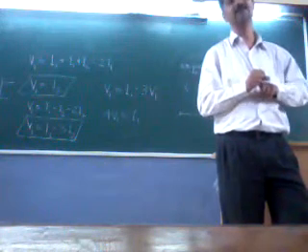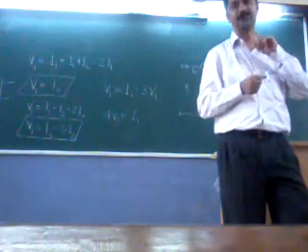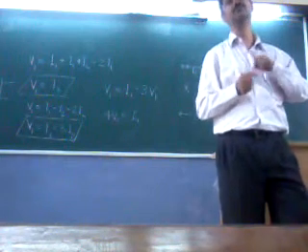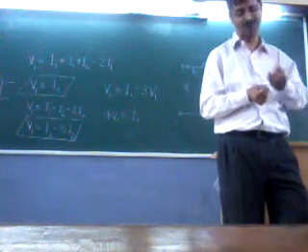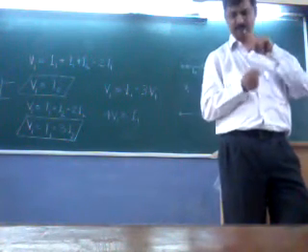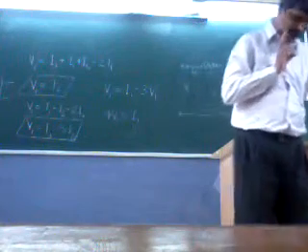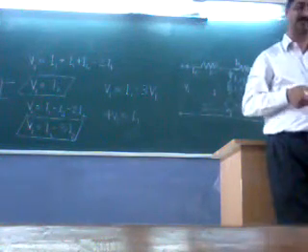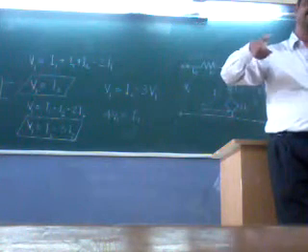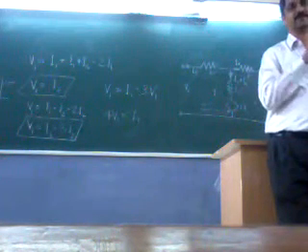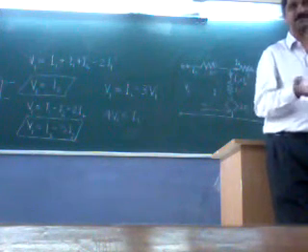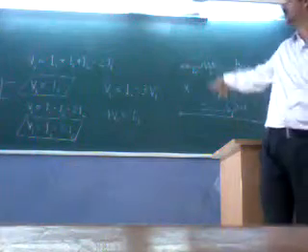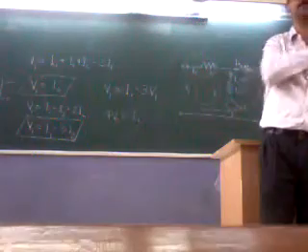Whereas here now we are specifically computing the different network functions. We are more interested in the transfer function. There are two kinds. One is the impedance function, called a driving point function because we take the ratio at the driving point. Others are transfer functions: voltage transfer or current transfer, or transfer impedance or transfer admittance. In this case, we have to compute it for a given condition.